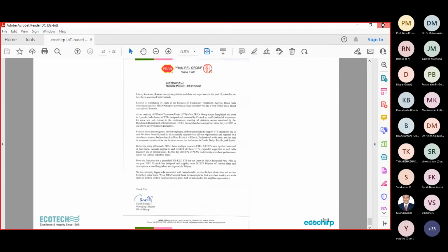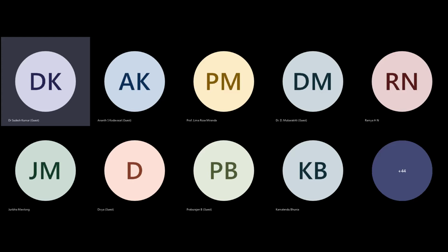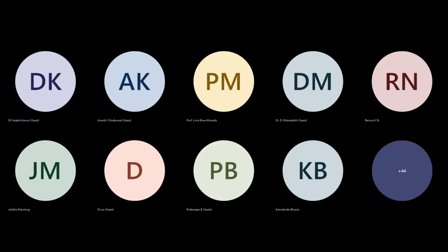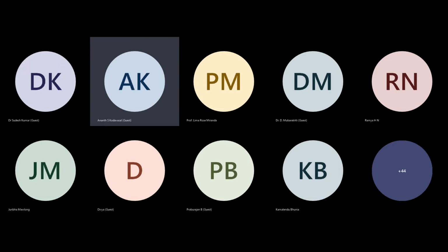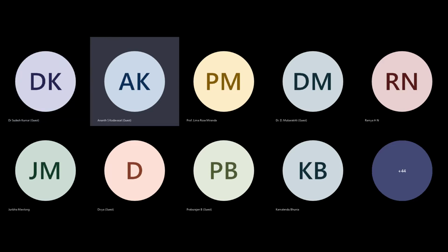Anand sir. Yeah. Which type of polymer you used in the last 2 or third last slide? You have mentioned some polymers. This is for sludge dewatering. We prefer the cationic polymer. GE makes a good polymer. I'm not able to get the name directly. Many manufacturers have these polymers.